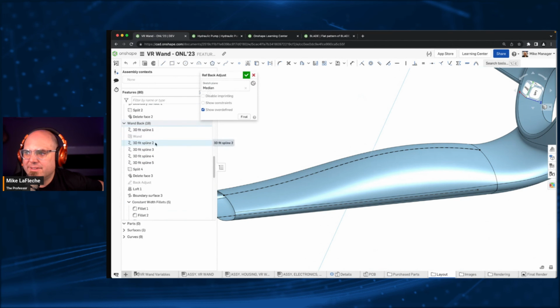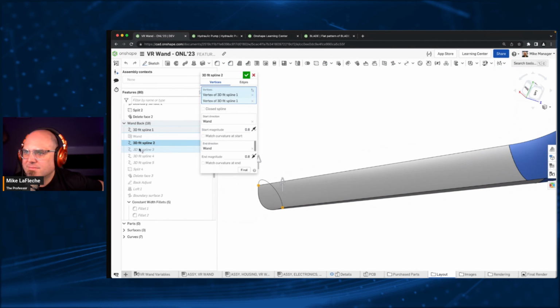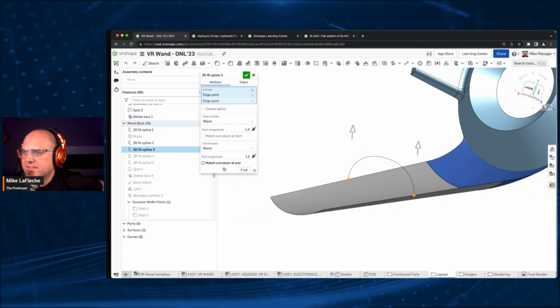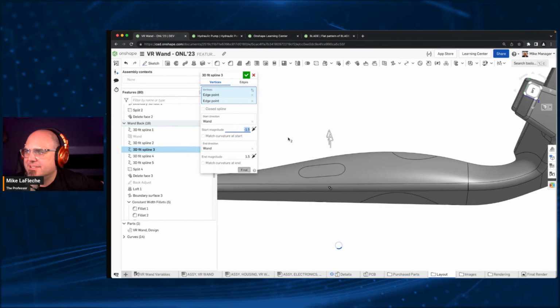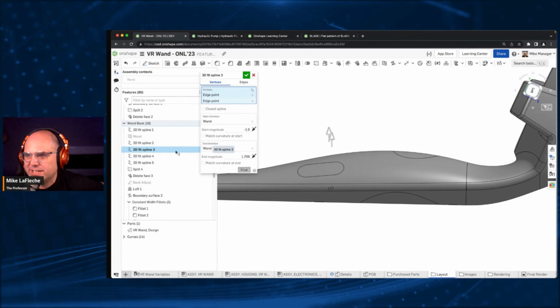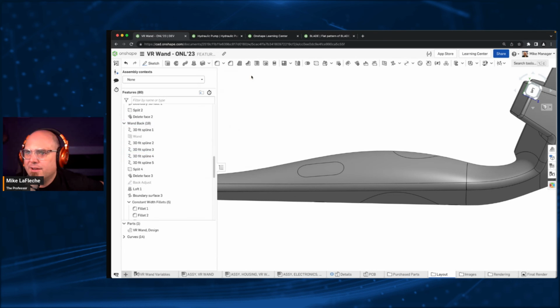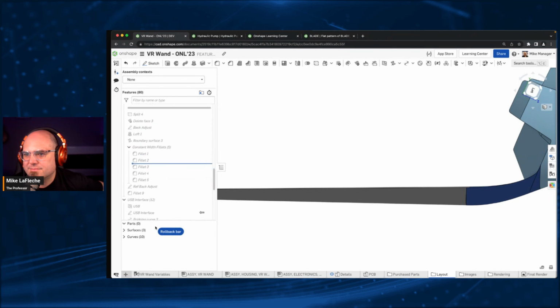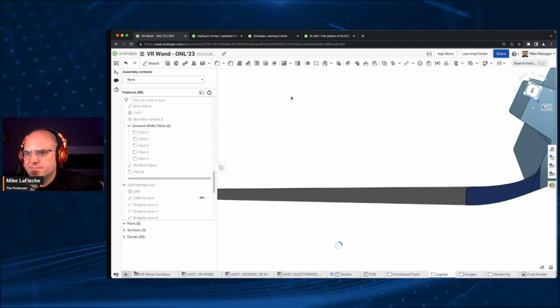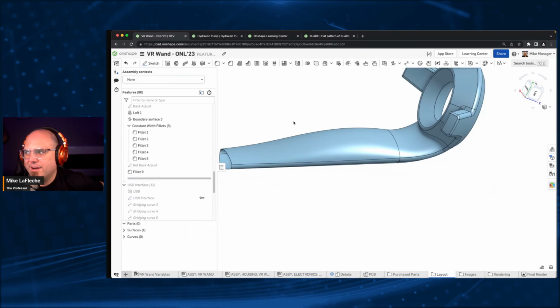Or did I use that with a fit spline? Well, yeah, here we go. So I've hit the final button. The final button's your friend when you're doing like push-pull crazy modeling with surfaces, right? So as I start modifying this shape, I can change the magnitude of this shape right here. Let's see, it's rebuilding the full tree. A little trick is to roll. Let me cancel that. We'll roll to here. So that way you don't have to rebuild the whole model while you're making changes, right?